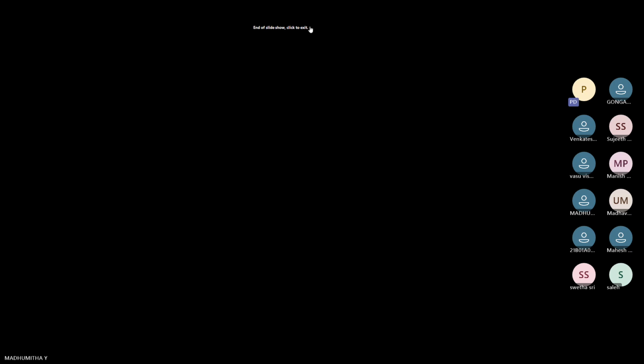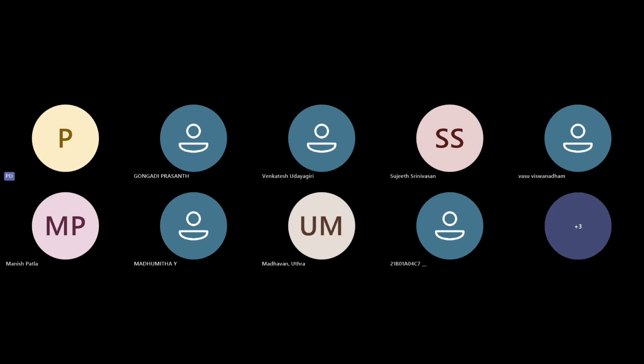So that is all about today's demo session. In this demo session, we have covered the domain and the top-level physical design inputs, and then every stage of physical design, which is synthesis, floor plan, power plan, placement, CTS, routing, and sign off.